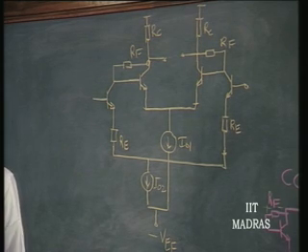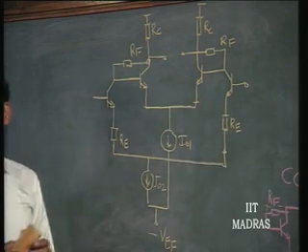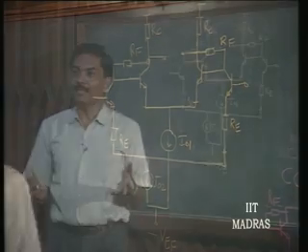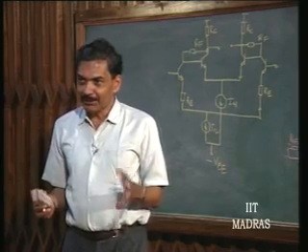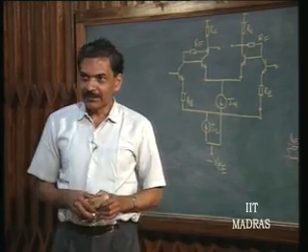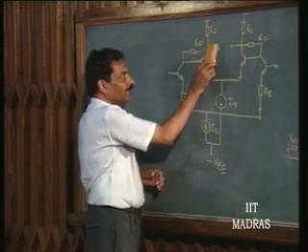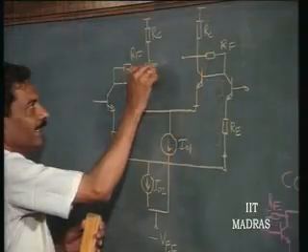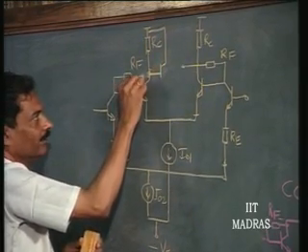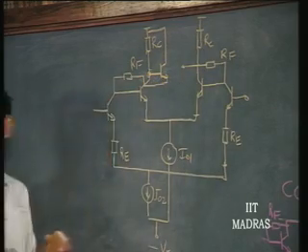These are going to fix the biasing currents here. And if you want to still use a wideband configuration, you can still cascade a common collector output stage. I mean, we are very liberal with the transistors now. So, instead of taking the output here, I will just put a common collector stage here and then take the output here, right.